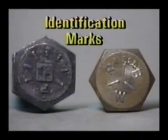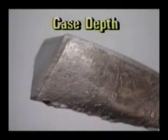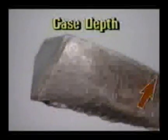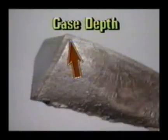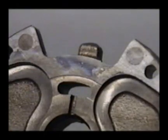Sometimes low-strength parts can be identified by markings. Bolts, for example, often have identification marks that indicate their relative strength. The left bolt with more radial lines indicates higher strength than the bolt on the right. A part may have low material strength because of improper case depth. Case depth should be observable on fractures, so if we don't see it, we should gather more facts in this area. Identify which indicator of low material strength is present on this part.